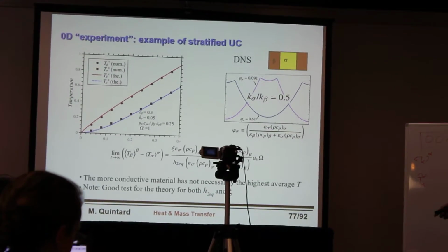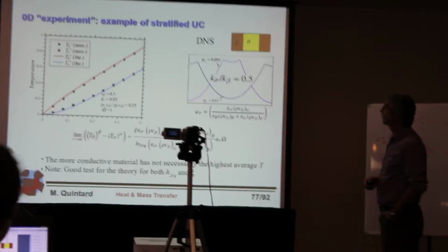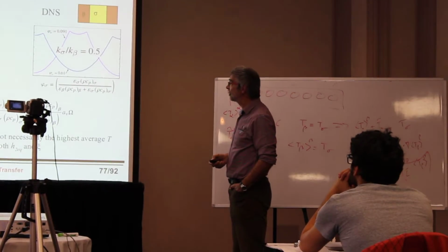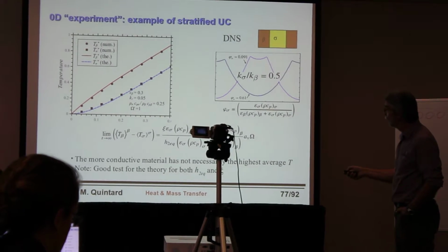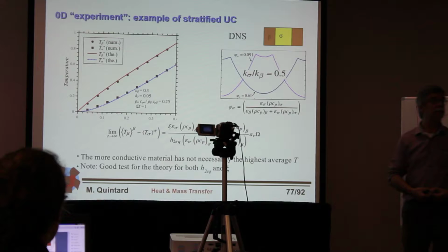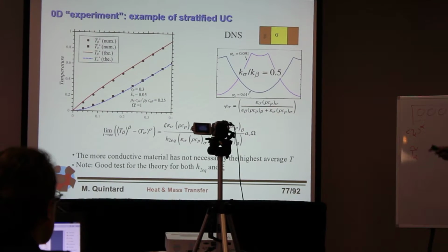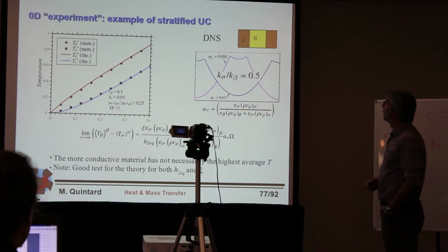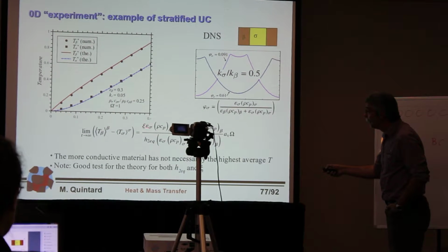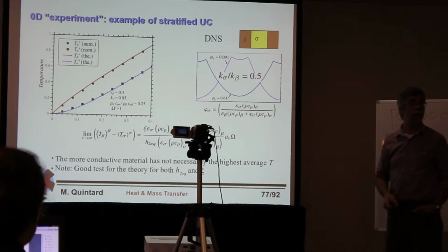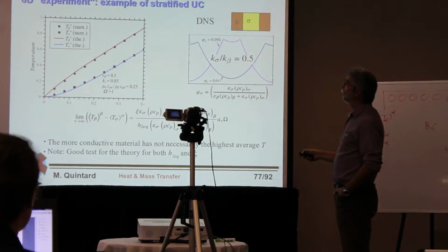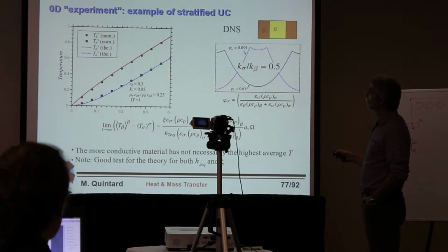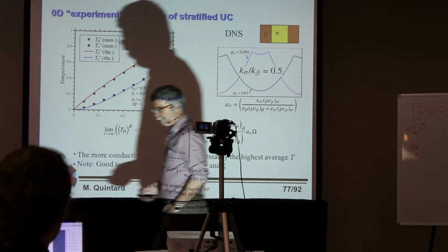And this difference can be predicted by the two-equation model with this distribution coefficient. And actually, the math gives the following result. So you have a difference that depends, of course, on omega. If there is no omega, there's no difference. And it depends on the heat capacities of the system, and it depends on the distribution coefficient and the exchange term in the system. There is a competition here between the heat that is exchanged between the two phases. And the points here are direct numerical simulation predictions, and the curves, the red and blue curves, are the model predictions. So it works